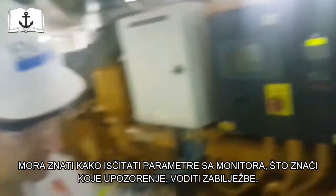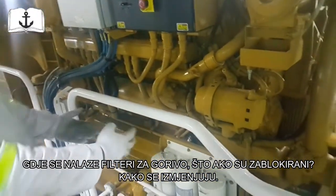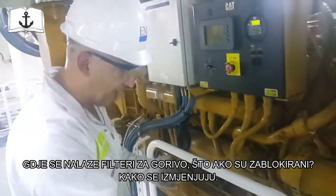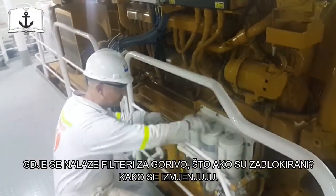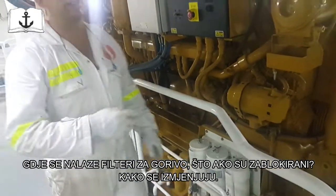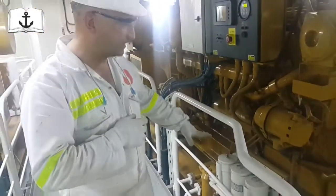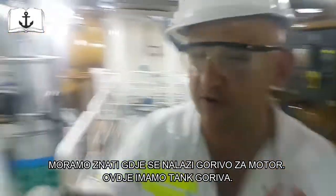The important thing is also that we need the fuel, of course. So you should know where the fuel filters are and how to react when a filter is blocked. You can always close one filter and change it on a running engine, it's no problem. Another thing is that you need to know where the fuel is located. So we have the tank there.